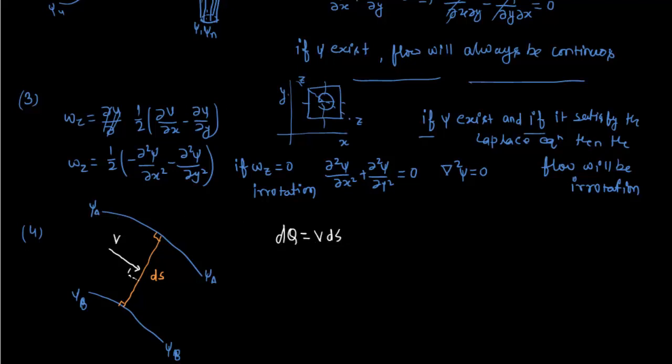But now in this case this velocity has two components, one in the downward direction, that I'm saying is v here, and one in the horizontal direction, this is u here. So u is in the positive x direction, so this is a positive value, but v is in the downward direction, that is the negative direction, so I'm taking this as minus here. Similarly ds also has two components, because area is a vector quantity.